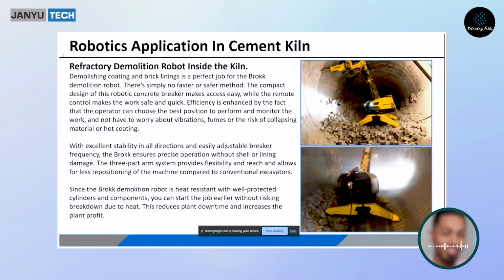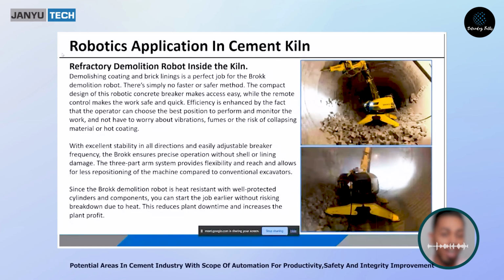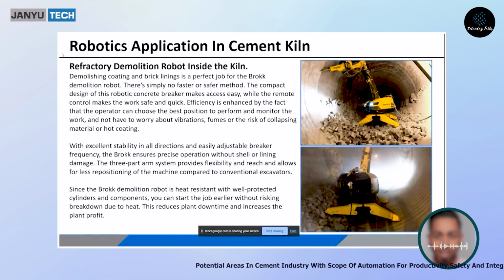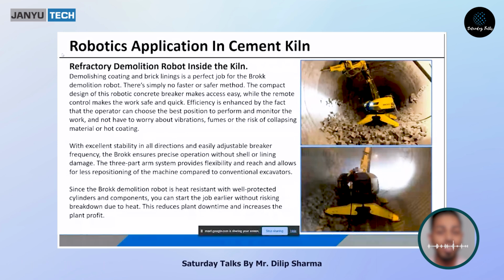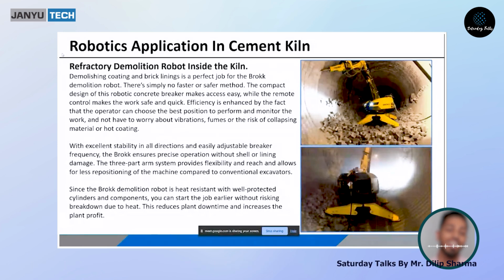So what are the qualities we test, sir, after taking the sample? The quality issue is basically the cost. The money you are paying for, you are not getting it. We test gross calorific value and moisture; these two are important. Then ash gives a fair indication, as ash has a correlation with gross calorific value. We'll discuss this, sir.